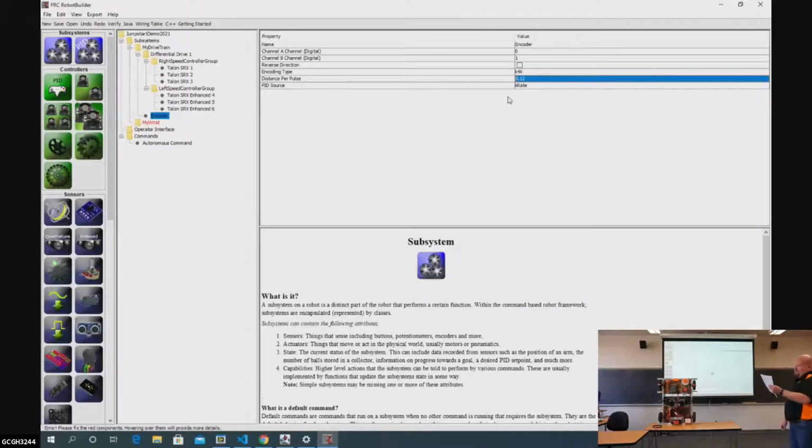If we take that value, 24 divided by 2048, we'll get a number of 0.012. So that's going to be 0.012 inches per tick of the encoder. So when we program our autonomouses, we'll have a more accurate, we can say, go 24 inches, it'll go 24. If that's not quite far enough, we can adjust that using real life user units. And that finishes our drivetrain for the day, for this moment.